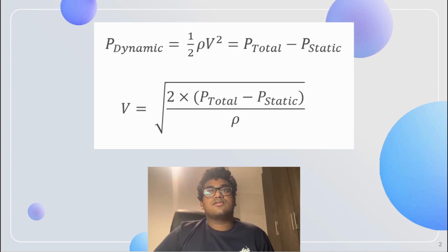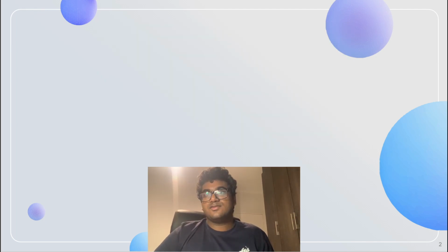The steady increase from 53 mm to 87 mm across the velocity range strongly supports the theoretical prediction that as velocity rises, static pressure decreases while stagnation pressure increases.